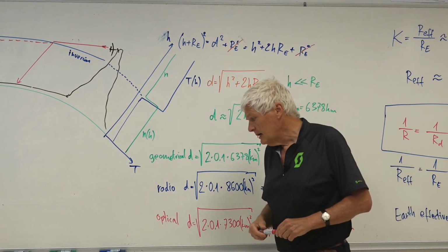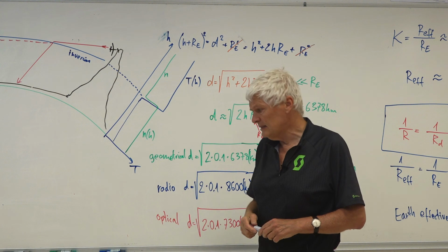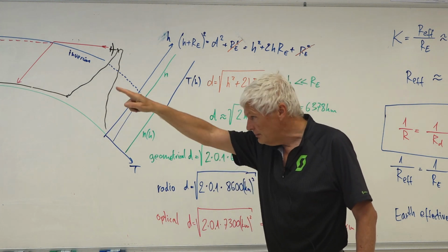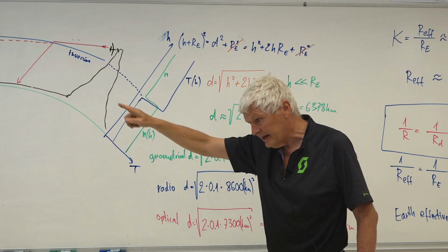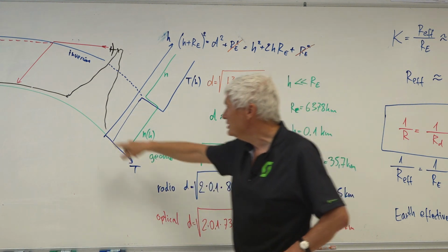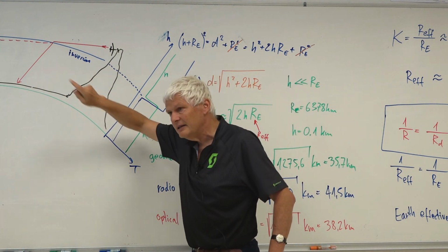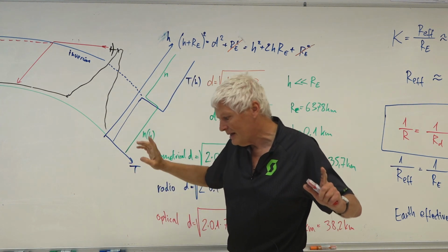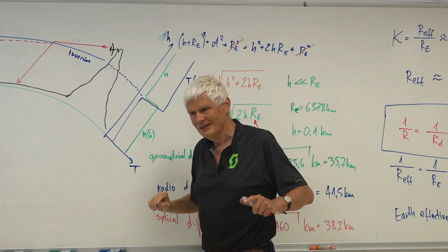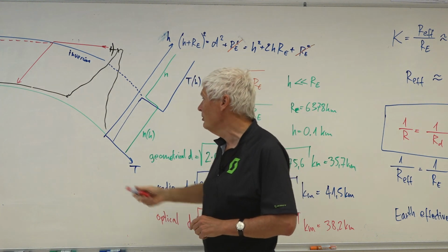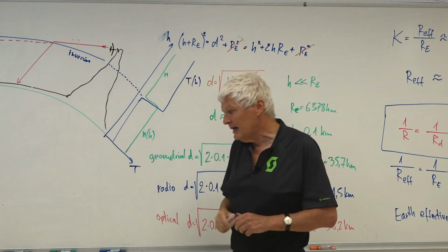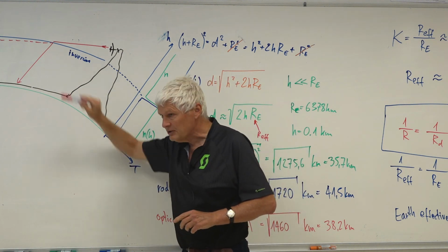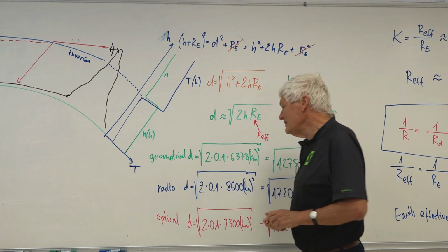In a practical experiment, I have a link that is 90 kilometers long, from Kobariški Stol to Krim. It goes over Ljubljana here. And in certain meteorological conditions, when I have fog in Ljubljana, that link drops down by 20 dB. I measure, all of the time I have telemetry, the signal level on this link. And this is a real problem. It was a problem also for our broadcaster. They had a link from Nanos to Krvavec, and that link was also dropping down when there was fog in Ljubljana.